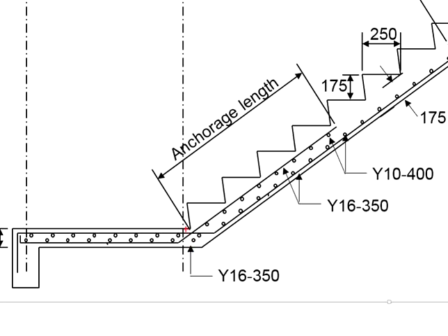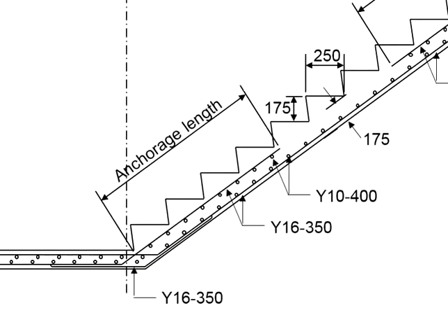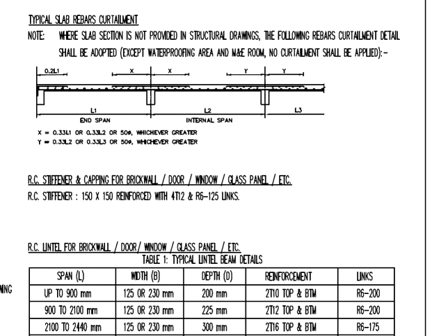However, such an arrangement can lead to a hinging process here. In order to prevent the hinging failure, we provide a tension reinforcement bar here. And this tension reinforcement bar has to be continuous. This is not two pieces of reinforcement bar. Instead, it is one single reinforcement bar bent at this angle. Again, for the required length here, probably you can adopt the principles here.